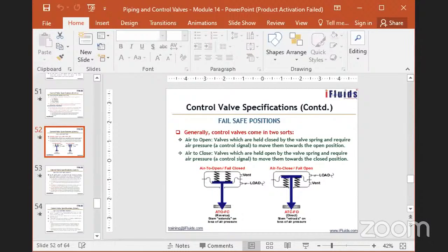Angle valves are very seldom used, only where you have a space limitation or some physical restrictions in the arrangement of the equipment, etc. Very specific requirements. One more important angle valve is in the Christmas tree, where we have a choke valve. The choke valve is an angle valve where we experience a very large pressure drop.